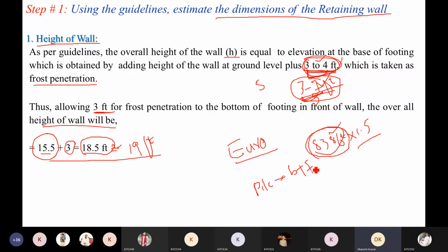Okay, now what does that mean? That pile can transfer the load with the help of the bearing capacity of the soil, and also with the friction between the soil and the concrete of the pile foundation. Some load is transferred through that friction, plus where it touches the bottom, on the hard strata, it has good bearing capacity, and from there too the load of the Burj Khalifa is transferred. So this is the thing. I am taking this into consideration because I just want to tell you that soil's nature is quite different.